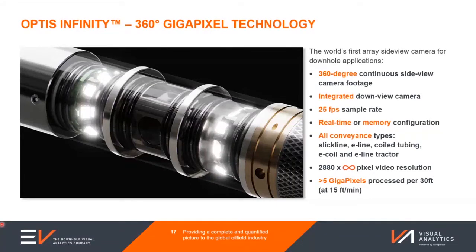So with that, we can actually move the system along the axis of the well like a conventional logging tool, capturing high definition, high frame rate video along the way as we go. And we can use this for a number of applications, from looking at scaling, corrosion, or even, in this case, we're going to suggest base holes in screens or perforations in production sections.